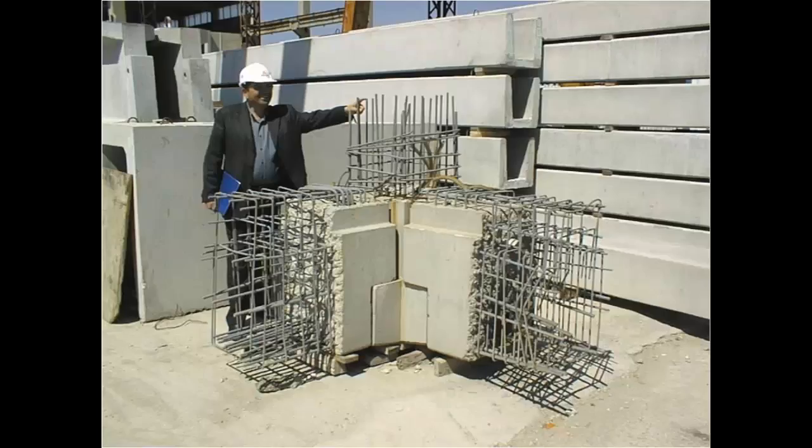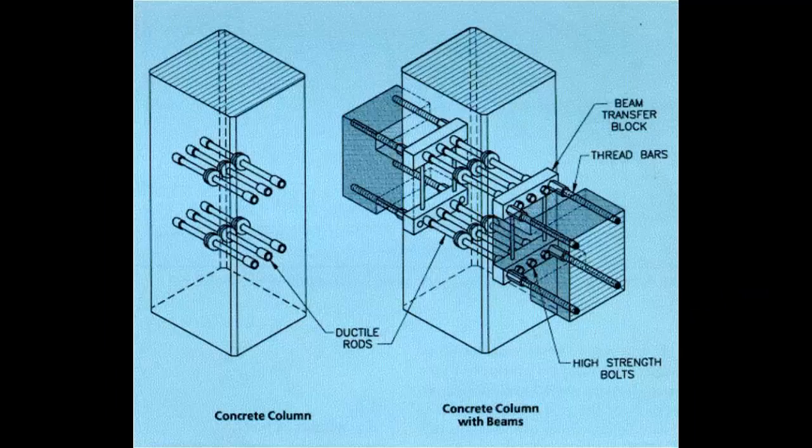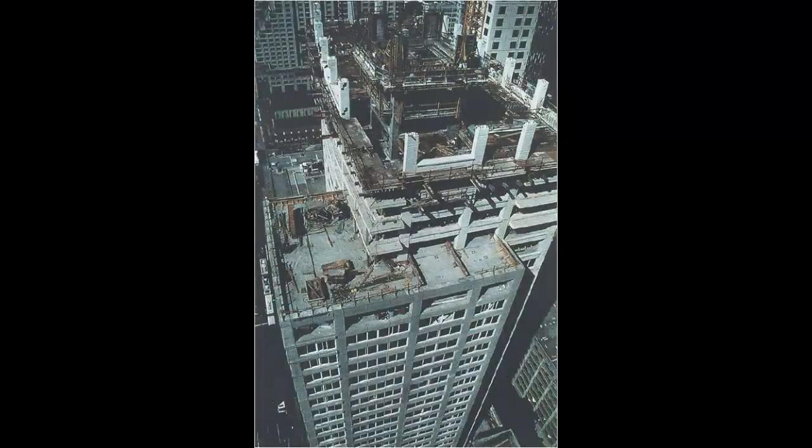A mock-up of a concrete beam-to-column joint shows the reinforcing used to transfer tension. The tension along with compression in the concrete allows bending to be transferred through the joint. These joints were used in a concrete building moment resisting frame. A concrete beam to column detail shows how bending forces are transferred through the joint, providing restraint of rotation. This is a joint between a precast concrete beam and a column. Joints like this were used to build a concrete skyscraper in San Francisco.